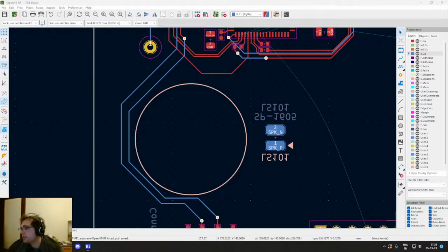But the way it's gonna be done is, anyway, the FPGA is gonna be part of the MCU firmware in a way. So we are gonna need to develop an add-on for the flasher, and then the flasher is gonna load the FPGA image or images in the NOR flash using the MCU, and then flash the MCU, something like that. So people are gonna be able to modify the image of the FPGA very easily. Basically just recompile your project and upload it, which is gonna take a few seconds.